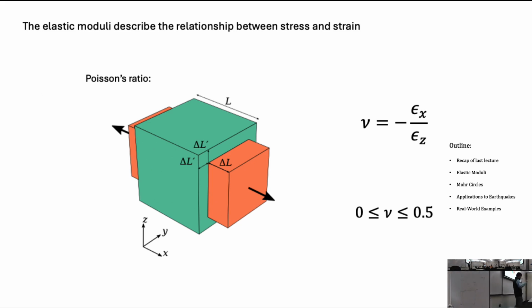Usually you apply a stress and, you think about it, I wish I had a ball or putty or something. If you apply stress to something in this direction, it gets bigger in the other direction. Usually, there are engineered materials that get smaller, which is pretty cool. So does that mean the Poisson ratio would be less than zero? Less than zero, yeah.